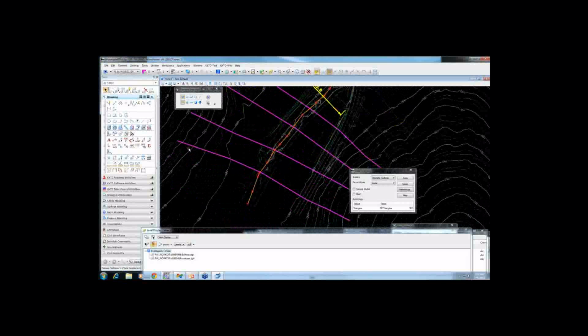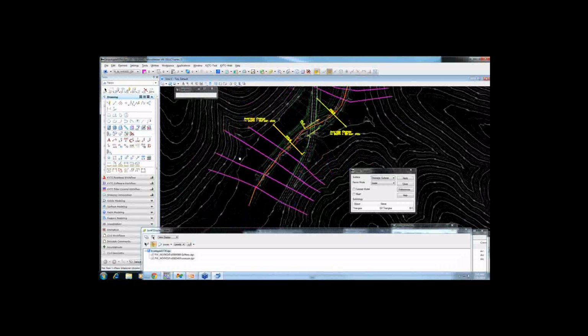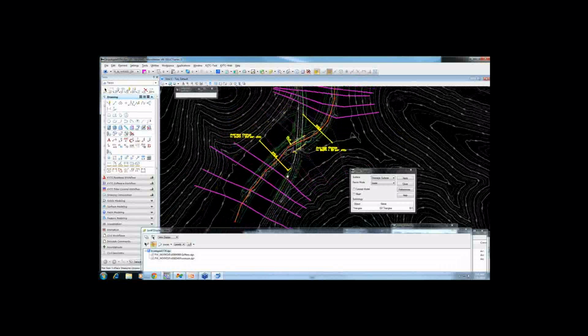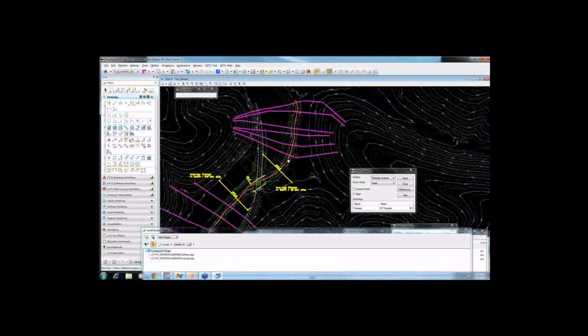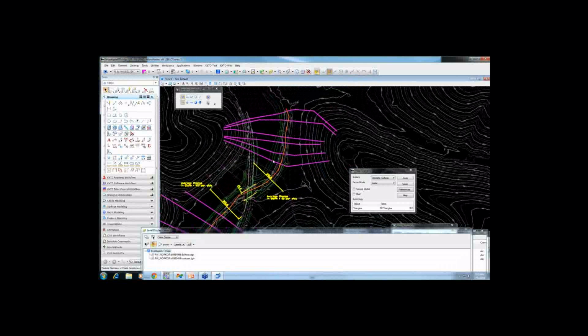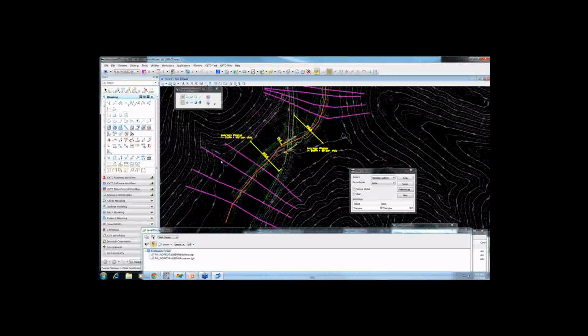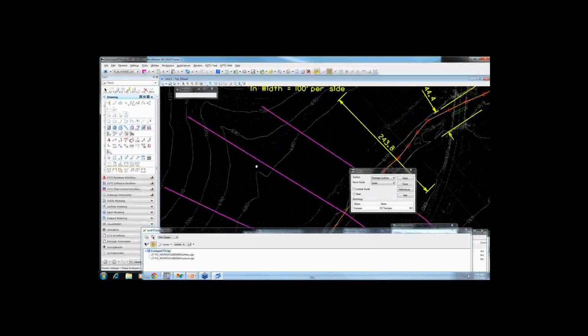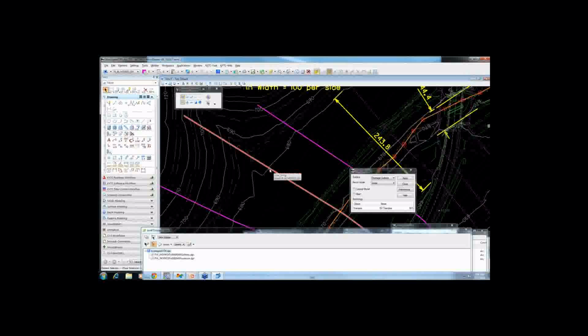And if you'll notice, these all look like they're going with the floodplain here. So a couple of things I want to point out is I may end up with a problem right here. If you'll notice, this cross-section runs up this drain here. And so I'm actually telling it that it has more area. I possibly could be telling it has more area than it really does. So just be careful when you see stuff like that. Take a look at it.